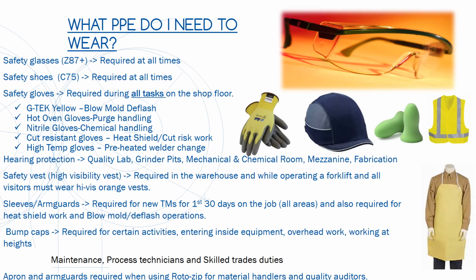Bump caps are required for certain activities: entering inside equipment, overhead work, and working at heights, maintenance and process technicians and skilled trade duties. The use of apron and arm guards are required when using RotoZip for material handlers and quality auditors.